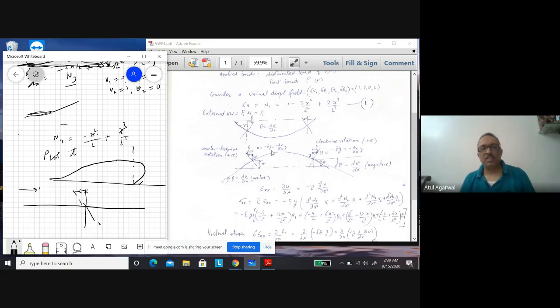You see our x direction is this. So displacement is in negative x direction. You see this rotation is positive theta. So our displacement becomes, this position is y. So we say u is equal to minus theta y. If this is a small rotation, we can say this displacement u, which is in x direction and in negative x direction, has magnitude theta into y.